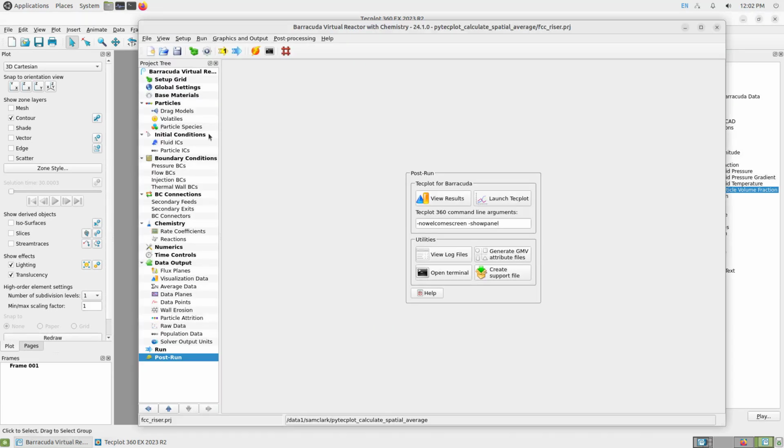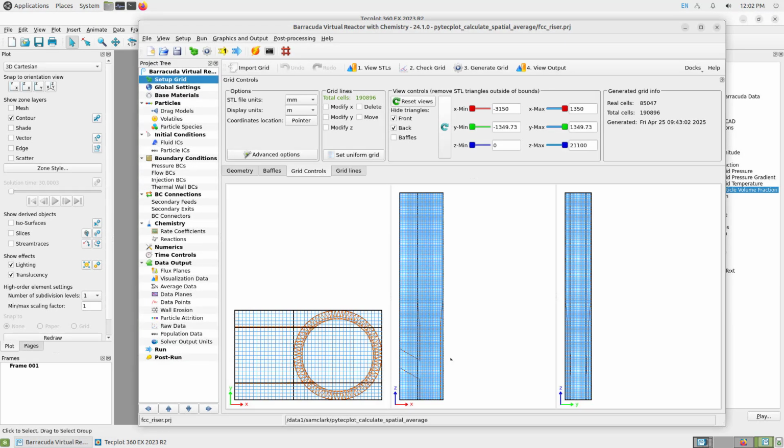In this case, if we want to get an axial profile along the z-axis, here I see that our k value goes up to about 194. So we have about 200 cells in the z direction. When I say we're going to use bins, what I mean is if we go with 20 bins, then each of those bins would have about 10 cells vertically.